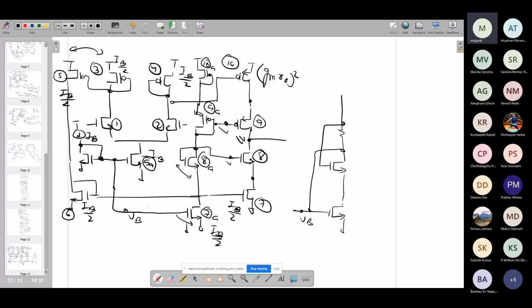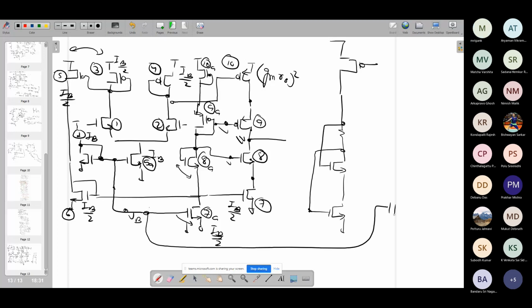One of the other options is, in this case, for example, if I push a current, whatever current you are having. So in this case, one better option, if you want to have a reduced swing Cascode operation, is that you can generate whatever PMOS current is required using a PMOS diode connected mirror like this.